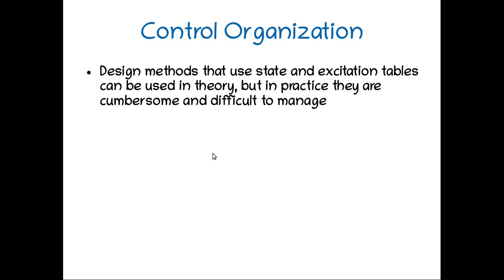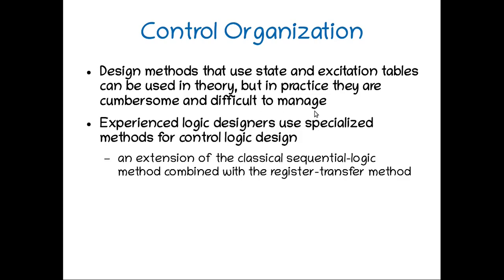Next, we have to design the control logic part in a digital system. Design methods that use state and excitation tables can be used in theory, but in practice they are cumbersome and difficult to manage. So experienced designers use specialized methods for control logic design. In our examples, we will use an extension of the classical sequential logic method combined with a register transfer method.